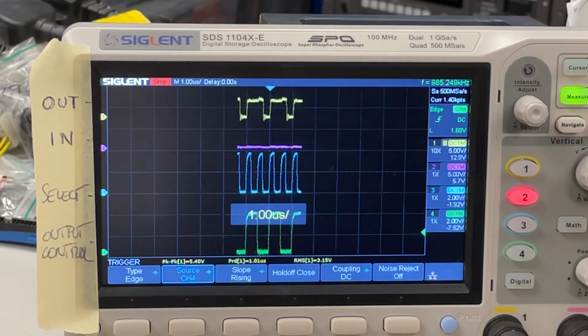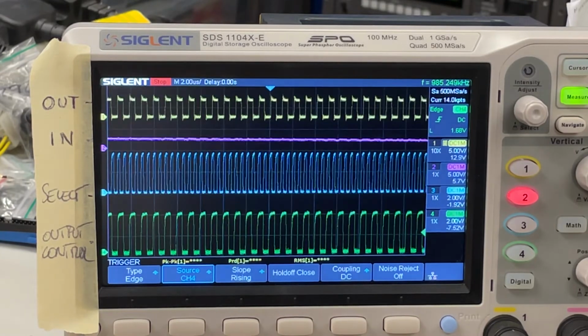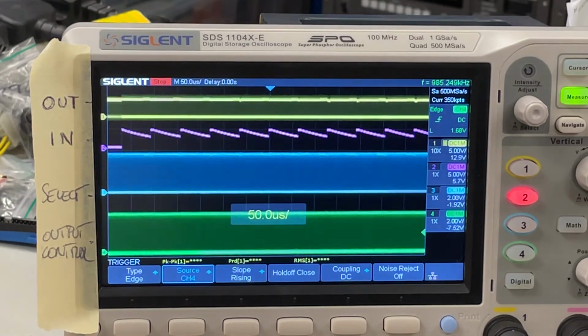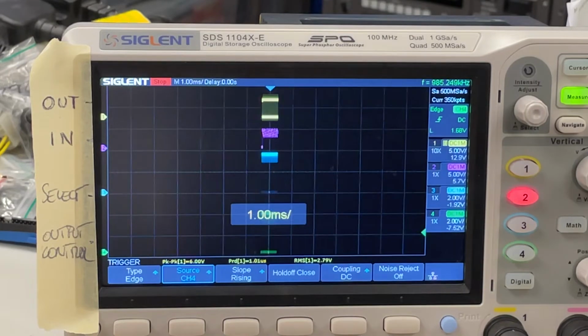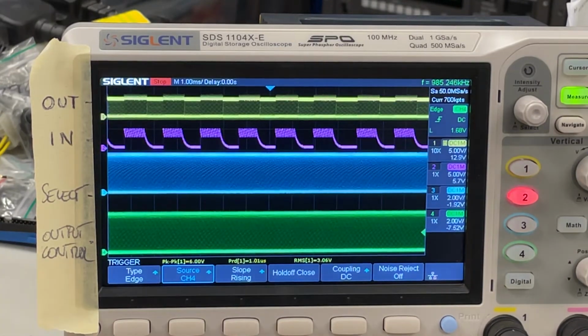If I take a reading, more than one, I see something strange on that input port. Let me change the horizontal scale here, and you see this thing, which doesn't really make much sense to me. It's doing this weird shape. And most importantly, the 64 doesn't power up. So it turns out that whenever I have a probe connected to this pin, the 64 doesn't power up.